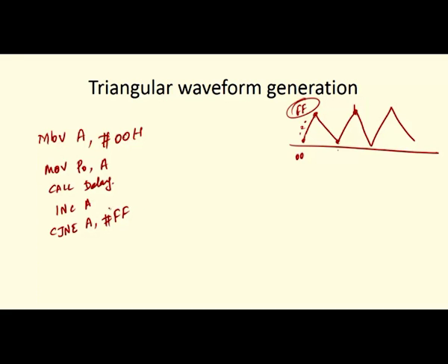So, the accumulator is increased from 0 to 1, then 1 to 2, up to FF. I want to repeat the process to raise the signal. So, I will give it here the label rise, the rising period, that is why I have given rise. From 0 to FF it started to run, the value 0, then it increased, then up to FF the process is repeated. Now, it has reached the value FF, what do you have to do now?